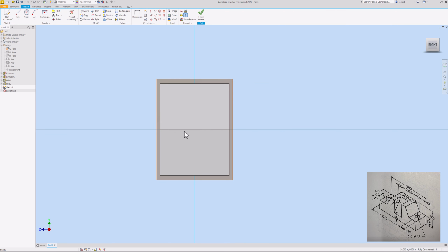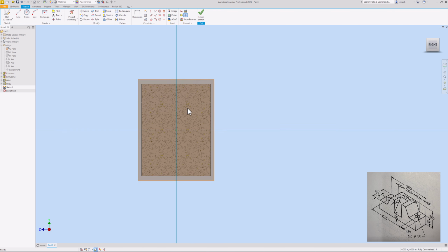So you notice the front half of that object is in our way. So I'm going to go down here to where you see the slice graphics tool. Click that. Now it removes that front part out of our way. So now I can just draw. Do I want to draw a line or, yeah, let's project geometry. I probably don't need to do that, but oh well. Let me just click these edge lines here.